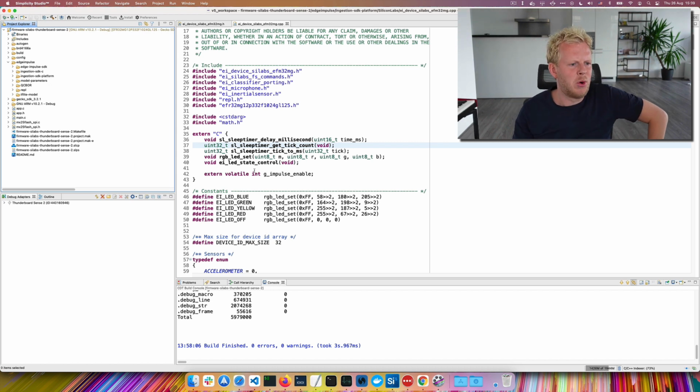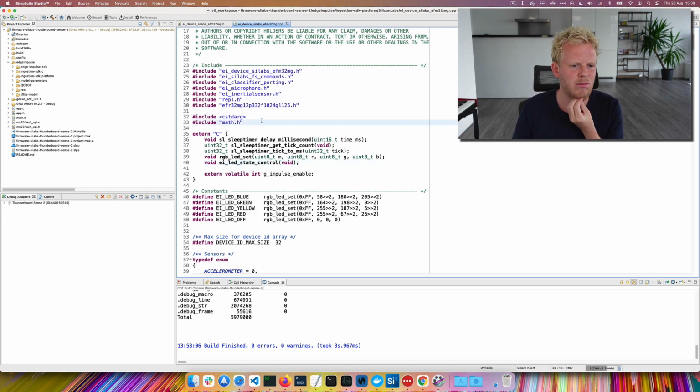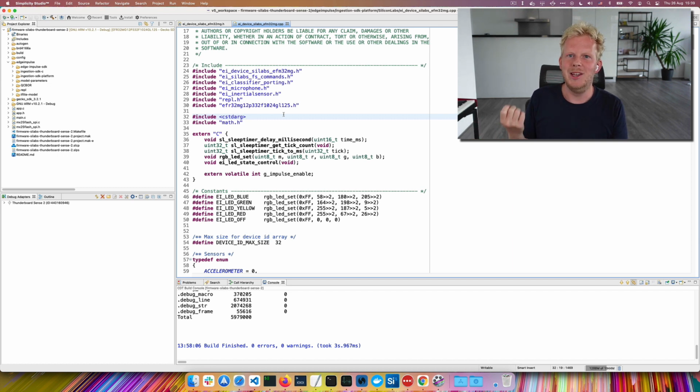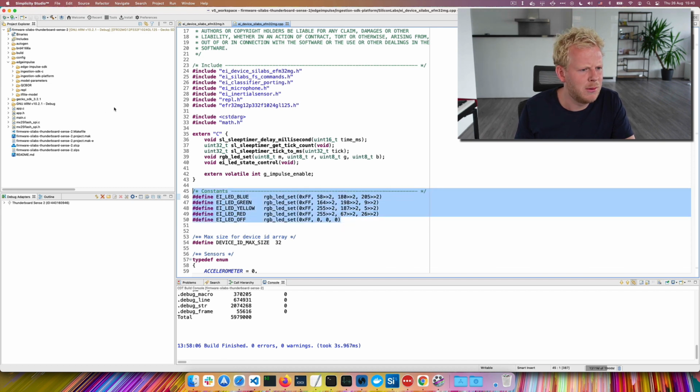So now when we build this project, we will get our model. What you get out is exactly the same firmware as we built earlier straight from Edge Impulse. Naturally, okay, cool, great, not that interesting. Let's actually make it do something interesting, for example, light up an LED whenever we hear pouring of water. We have some code here to turn the LEDs on and off. I'm going to copy that.